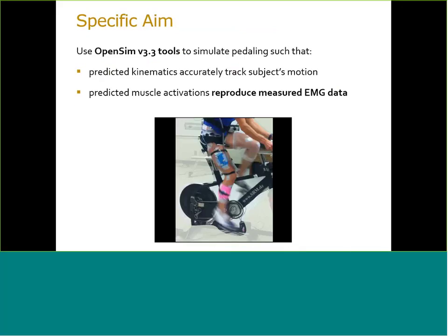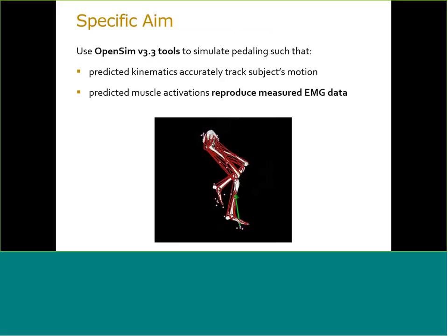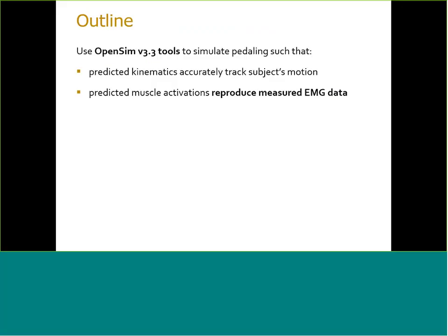Now, as a first step, we decided to generate some muscle-driven simulations of pedaling. Our specific aims were to predict kinematics that accurately track our subject's motions and predict muscle activations that reproduce our subject's measured EMG data. And if you're using OpenSim, this is often what you're trying to do. Now for pedaling, we found out that doing this was harder than we expected. So our goal for today in the webinar is to share some tips that we learned for simulating tasks like pedaling that have substantial hip and knee flexion.